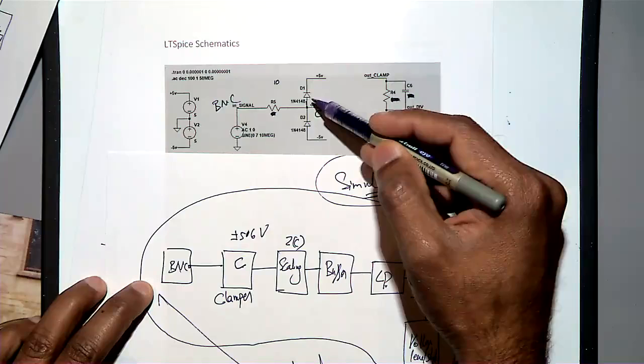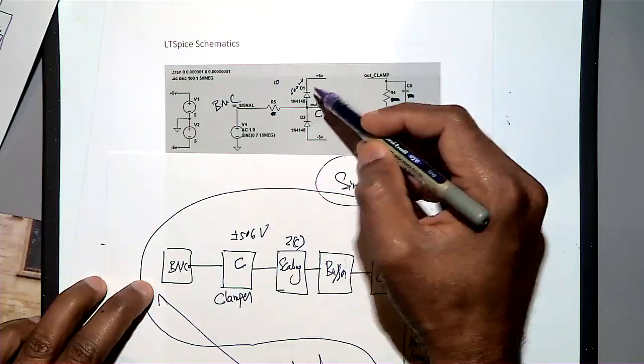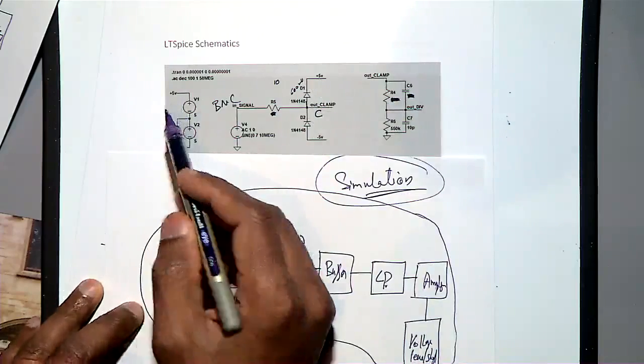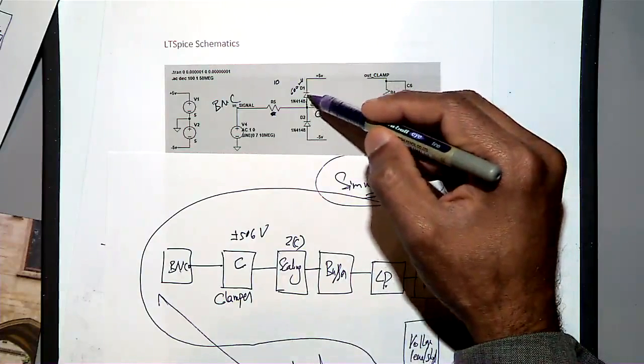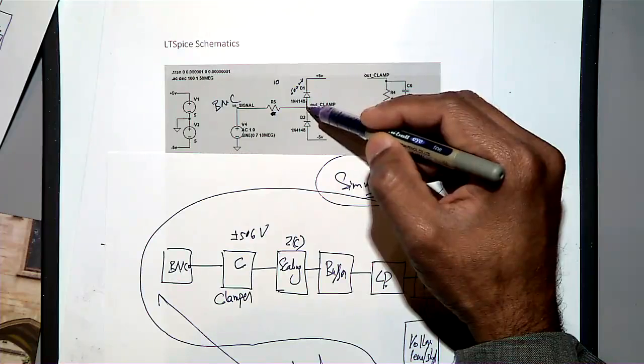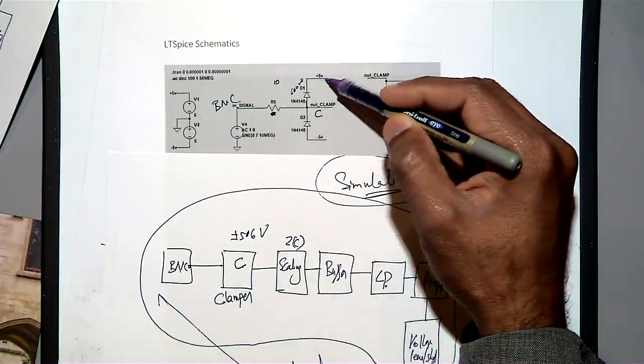No, sir, the diode will have its own voltage. Yeah, so that is around 600 millivolt. So that is the reason we said plus or minus 5.6. So this will be dropping 0.6 volt, and then it will never become more than plus 5.6, because you got plus 5 volt.